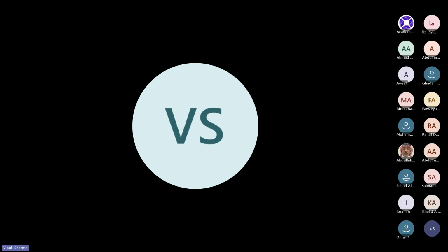All that setup needs to be done before you can do an actual open loop gain measurement, so it's not so easy or simple. There is a background setup needed, on a breadboard or PCB. You have to make a test circuit for that, and only then can you do that measurement.